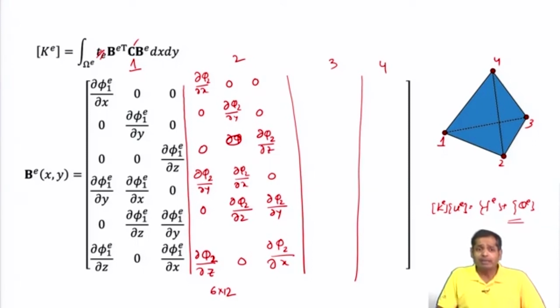Sometimes getting the solution of these equations for the entire domain is difficult, or we may not have a single equation for the entire system. So the idea is to break the system into small subsystems, such that for every subsystem we can write the equation, and once we have the information about every subsystem, we assemble all this information together to get the equations for the entire system and then solve it. This is the premise, the basic philosophy of the finite element method.